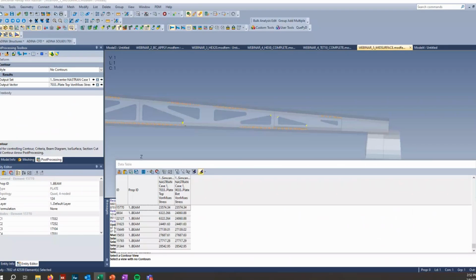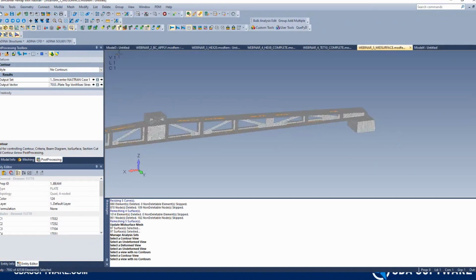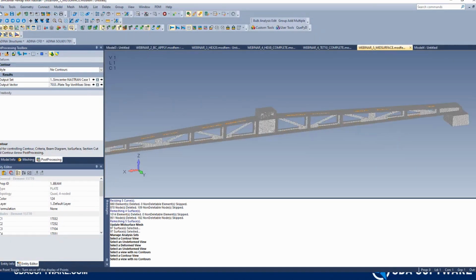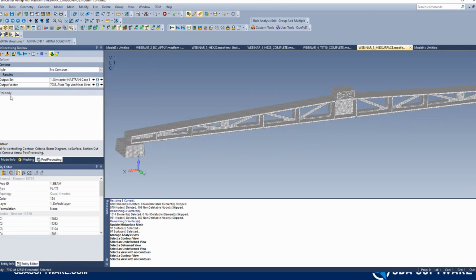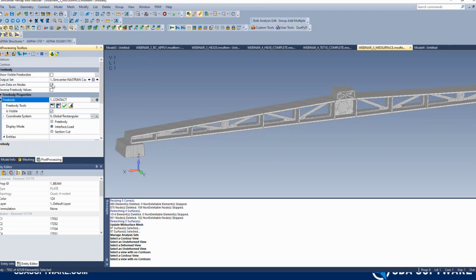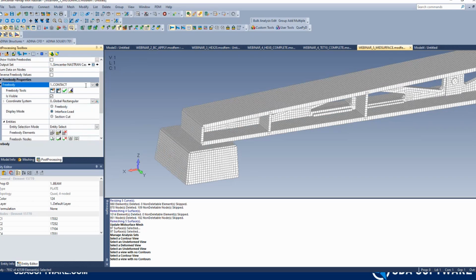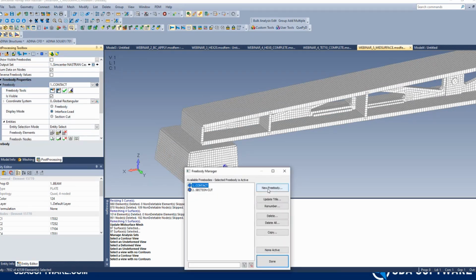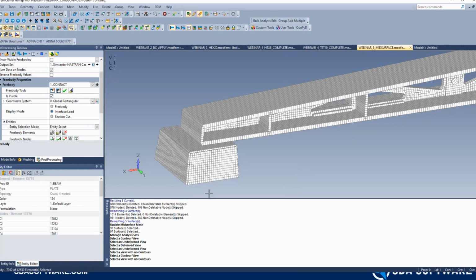One last thing we're going to show here is the free body tool. The free body tool is a very powerful tool in the FEA set here. It allows us to sum the forces across an interface. For instance, we would set this up by doing new free body and specifying the type of conditions here. In this case, we already have two that are set up.